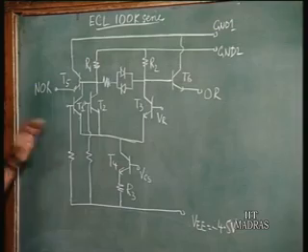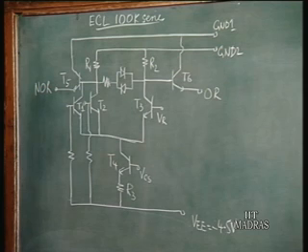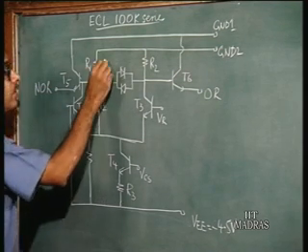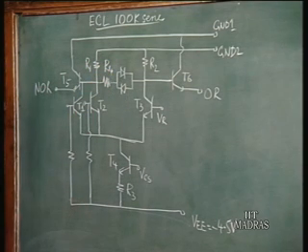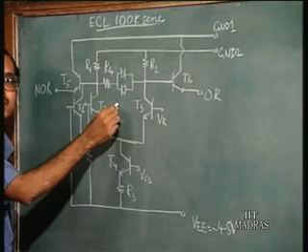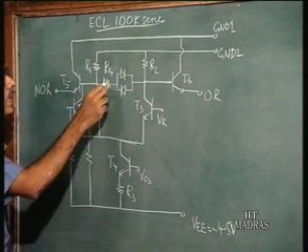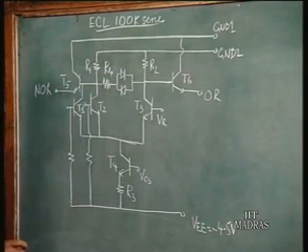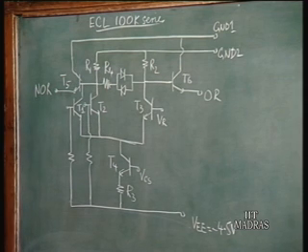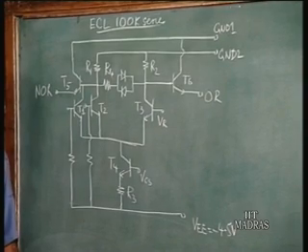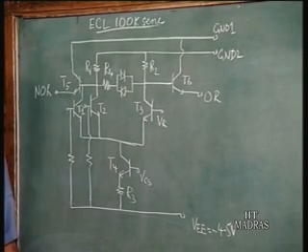So, on the blackboard here we have the circuit for the ECL gate of the 100K series. Now, as you can see, the modification on the circuit is a small part here which consists of two diodes connected with a resistance here. The purpose of this is basically for temperature compensation, that is, the circuit outputs should not depend on temperature. Let me explain it.